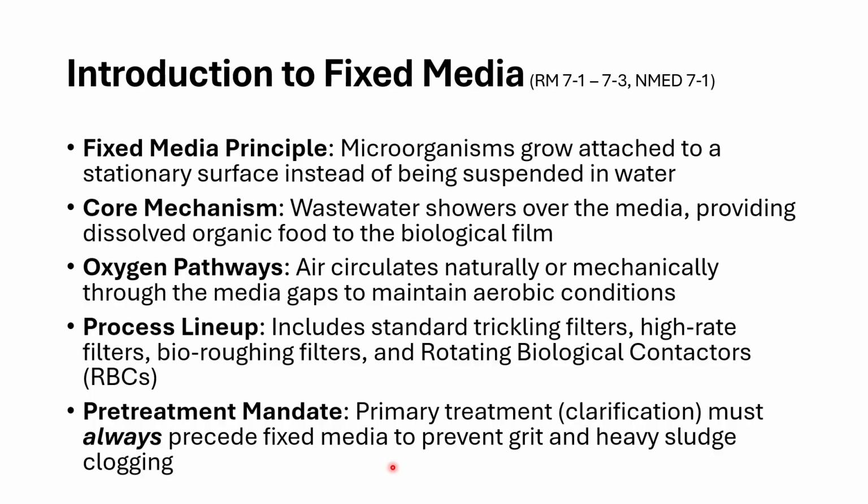This is a very important note right here. Pre-treatment. Primary treatment or clarification, allowing the heavier sludge particles to settle out, must always happen before we introduce wastewater to the fixed media. And that's going to prevent the heavy sludge and grit particles from settling into the trickling filter or clogging up our biological contactors. Very important concept here. It's a mandate.